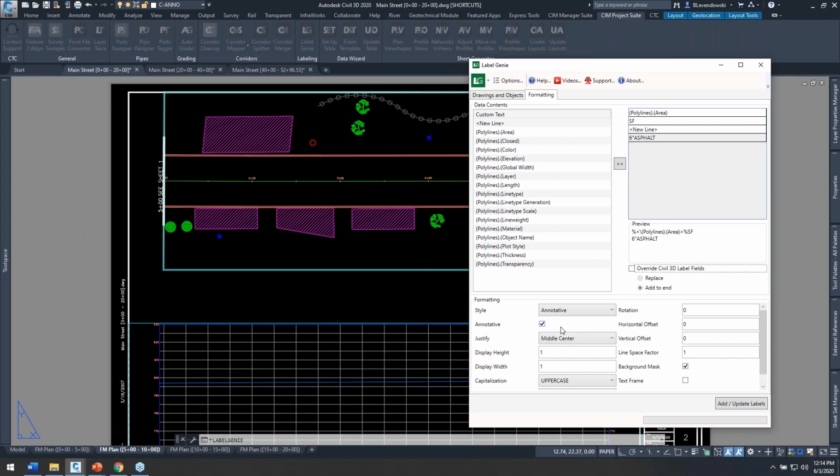And then down here, this is M text again, so I've got a lot of formatting options. What's the display height? I've got a height of 0.1 because I'm using annotative text, in fact. But here's all those text styles I can choose from. Those are what exist in the drawing. And then the display width, M text has word wrapping on it if the width won't fit the entire text string. So depending on what size you put here, it'll wrap text automatically.